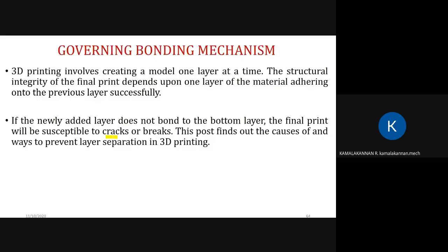Otherwise, there will be a formation of cracks or breaks. Why is there a formation of cracks? Because a layer has been heated and cooled, and then the second layer is printed over the first layer. If the first layer is already cooled down or solidified and gets heated again, there will be a chance of increasing the brittleness of the material. That is why there will be a chance of forming cracks or breaks.